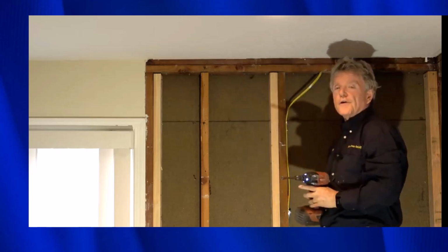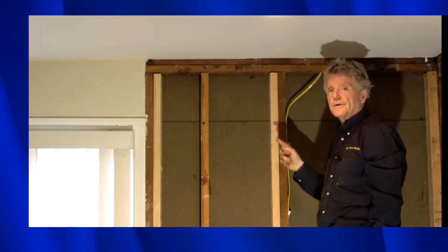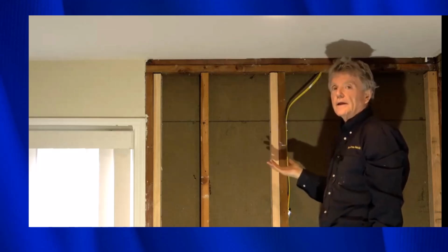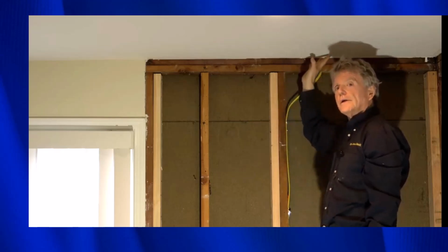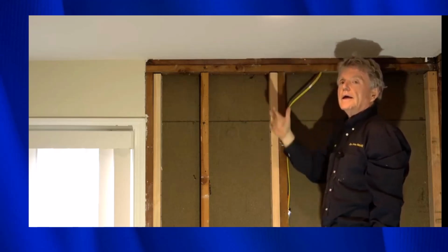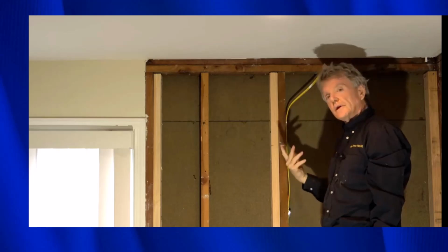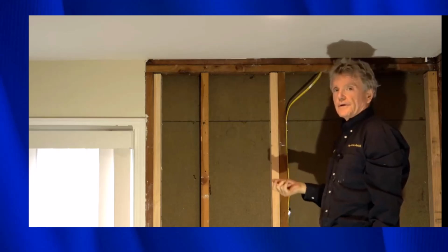And that can resist 400 pounds for each lag screw. You have to calculate how many you need, but it's a pretty simple affair. And this way we've saved the homeowner all the expense of tearing out the ceiling. It's a whole lot cheaper for the contractor, it's cheaper for the homeowner, and it does a really good job.